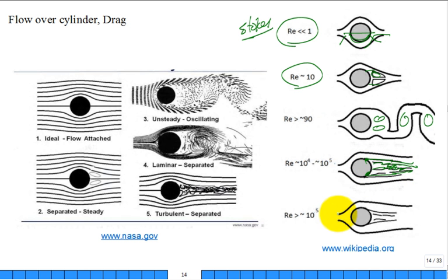You can get that point to move up quite high, but if it becomes turbulent flow, then it pushes back the separation point, and it becomes a smaller wake region because of turbulent flow. It's able to navigate and come around the backside of that cylinder. Does all of that make sense? Can you walk out of this class and repeat to your friends that type of story? Describe the flow around balls and around cylinders?